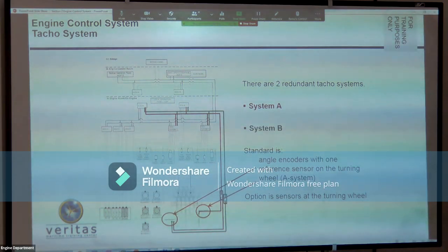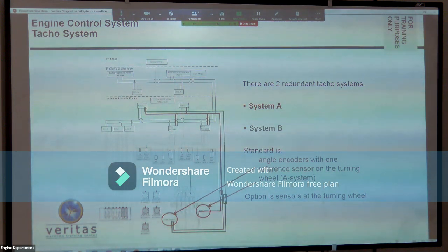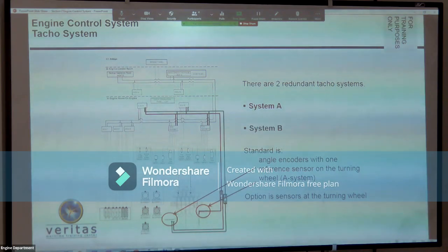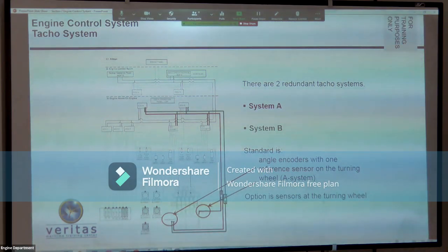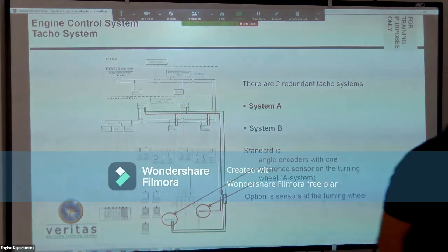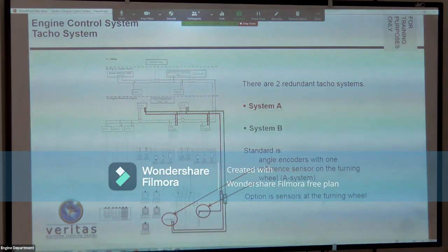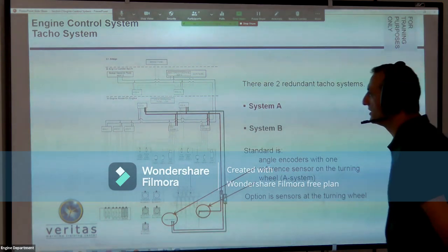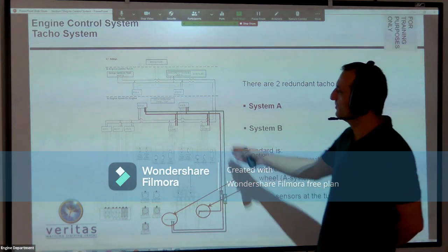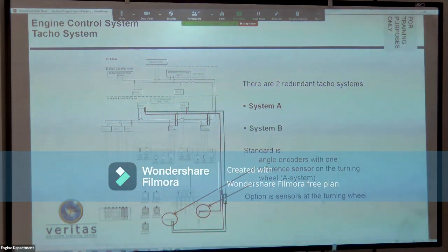The position of the crankshaft read by the encoder is transferred to all controllers involved in the combustion process. So the data from the encoder is transferred to the ECUs and CCUs. It is transferred to the ECUs to calculate the timing of the fuel injection and the fuel index, and transferred to the CCUs in such a way that, with the data package received from the ECU, the timing and the fuel index, they activate the mechanical components, fuel injection and exhaust valve, at the precise time according to the position of the crankshaft.